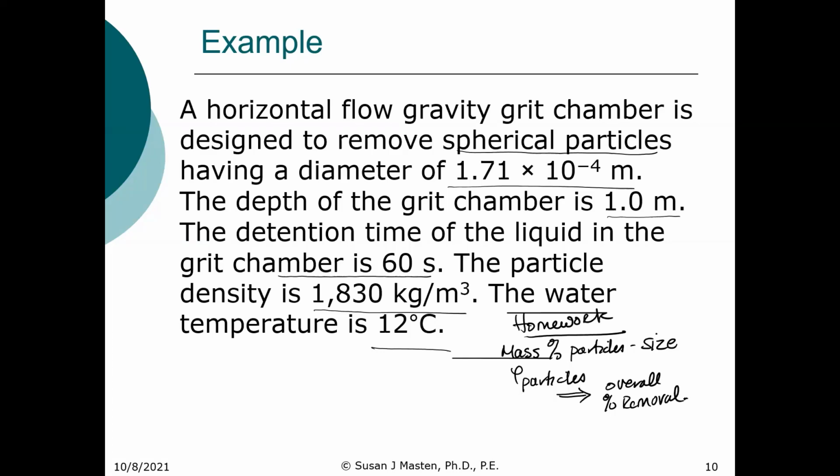What you would need to do is calculate the percentage removal for each particle size, and then do a weighted removal and add up the weighted removals.